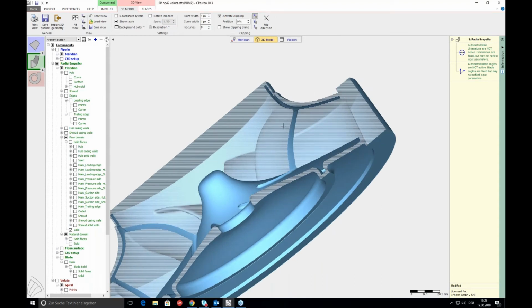As I said earlier, depending on the pressure difference that is generated by the pump, there might be some backflow, and of course then the inner part of the impeller will see more fluid flow going through that and will therefore decrease the performance because of the lower volumetric efficiency.